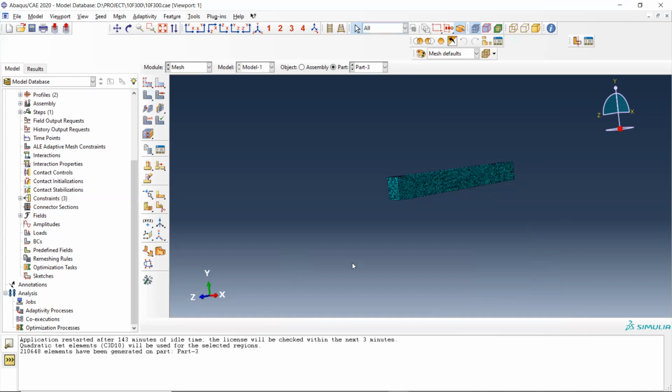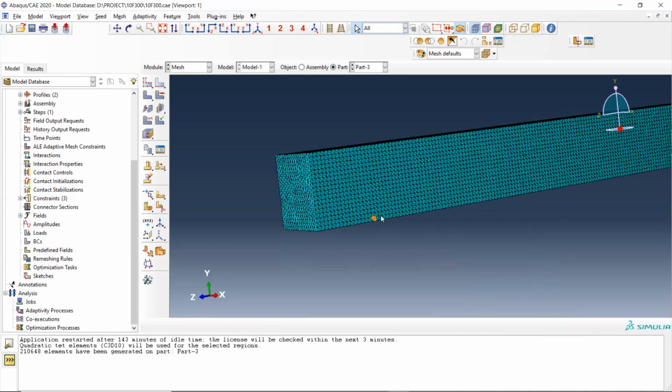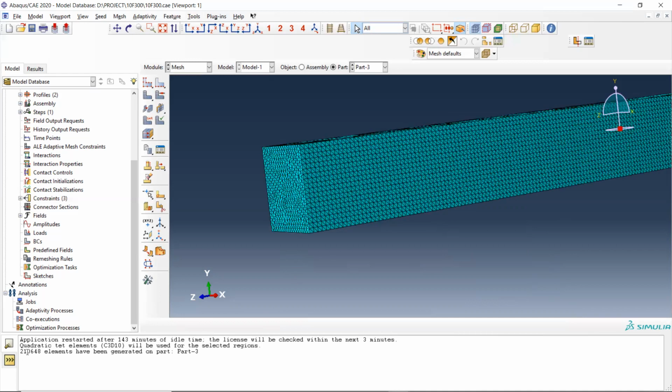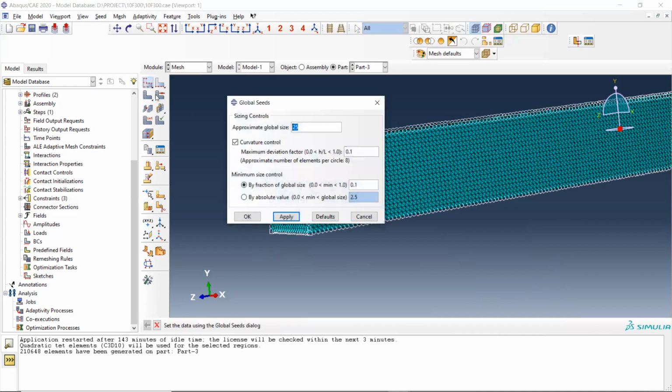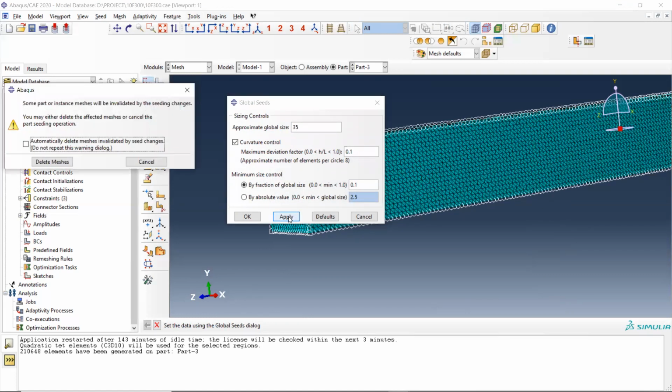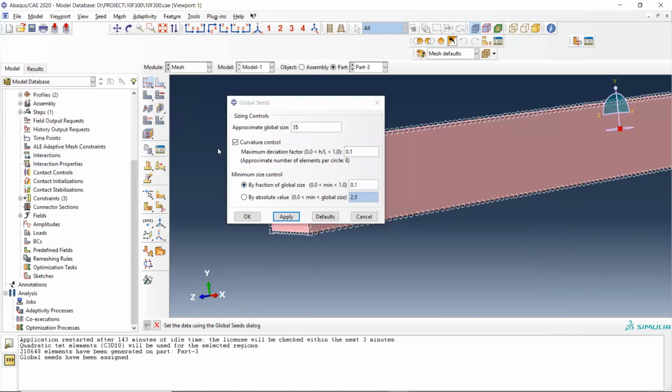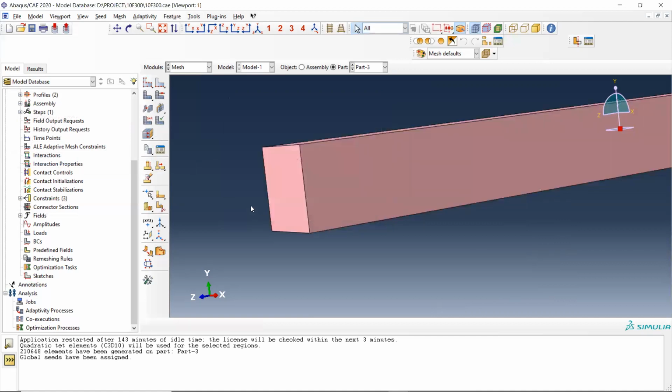Okay, so this is how you can do this, and it will work. But that is 2,10,648 elements, and that much is not required. So you can go to the size of this. Don't go for 25. Still, you can make it something like 35 also. Do it 50. 50 would be better. Yeah, we'll see that also.